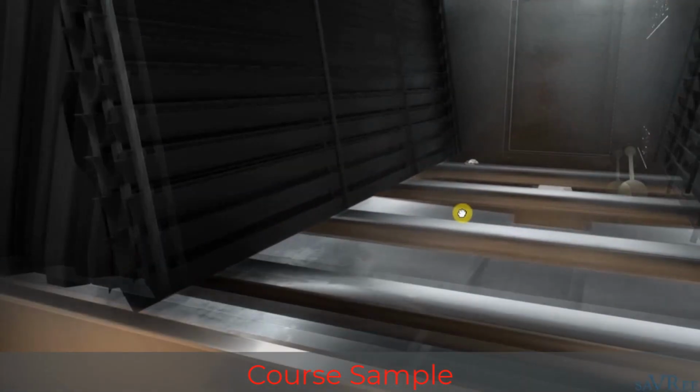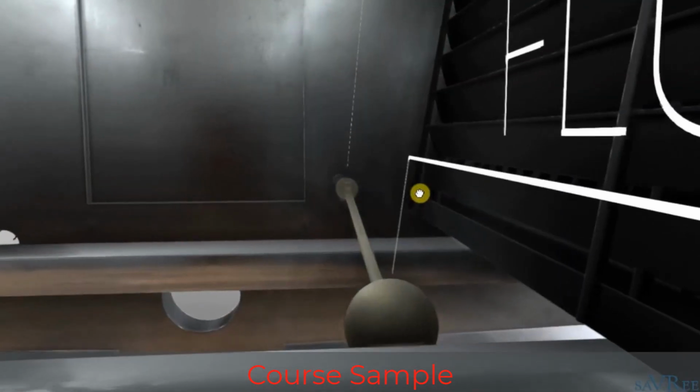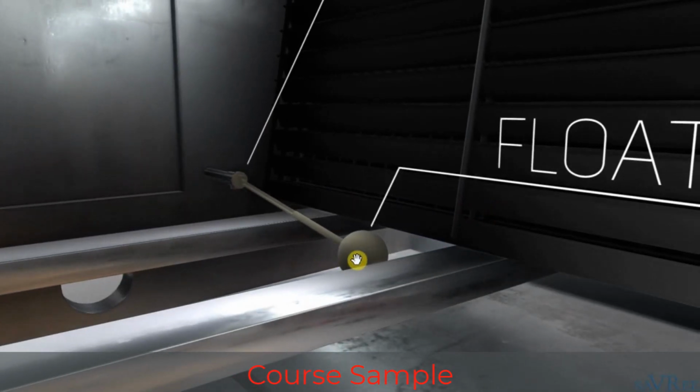If we go down into the base, we can see that we've actually got a weird kind of ball float mechanism over here. This float mechanism actually allows the lever, this entire lever here, to travel up and down. As it travels up and down, it's going to control the amount of water that's let into the cooling tower. The water that's let in is known as make-up water because we're making up for our losses. Our losses may be due to leakage, maybe due to evaporation or drift, and we need to replace that water so that the cooling tower doesn't run dry.